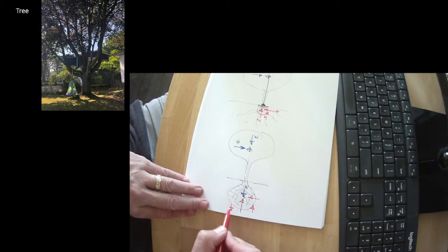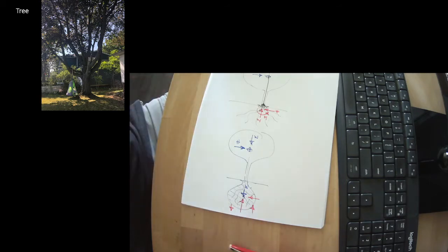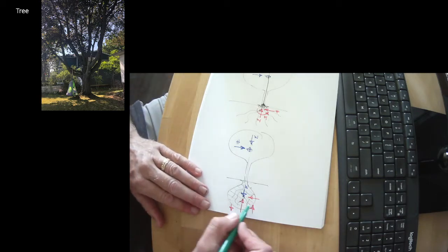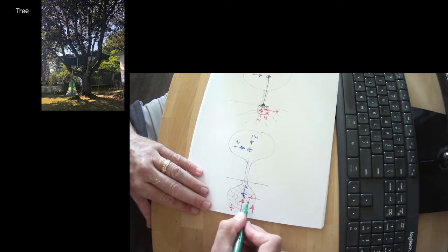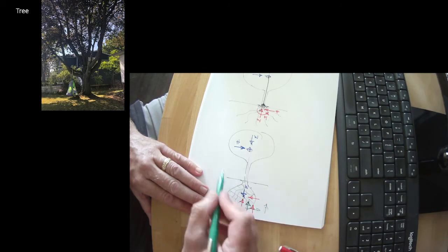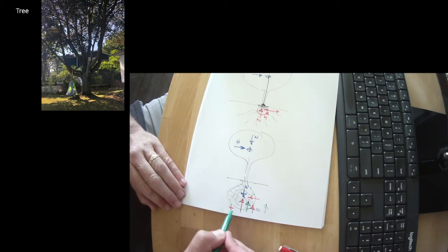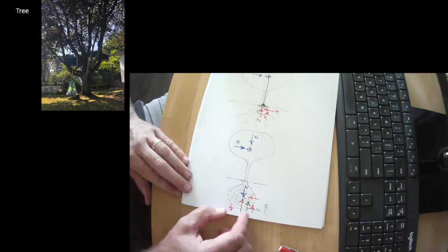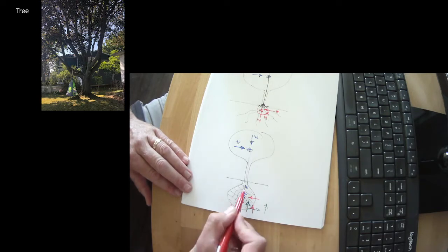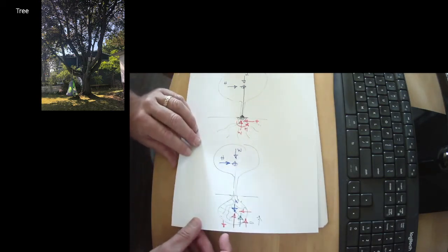We're resisting our vertical load, we have some pull out, we have some pull down, and if we take the resultant of those things, I'm going to represent the resultant in green. What we wind up with is the resultant somewhere here in the root ball. If the resultant winds up outside of the root ball, we're in trouble, we're toppling over, and that's what happens in a hurricane. But because the root ball is large, our resultant doesn't have to lie straight in the middle of the root ball. It moves over so that we can resist overturning loads.